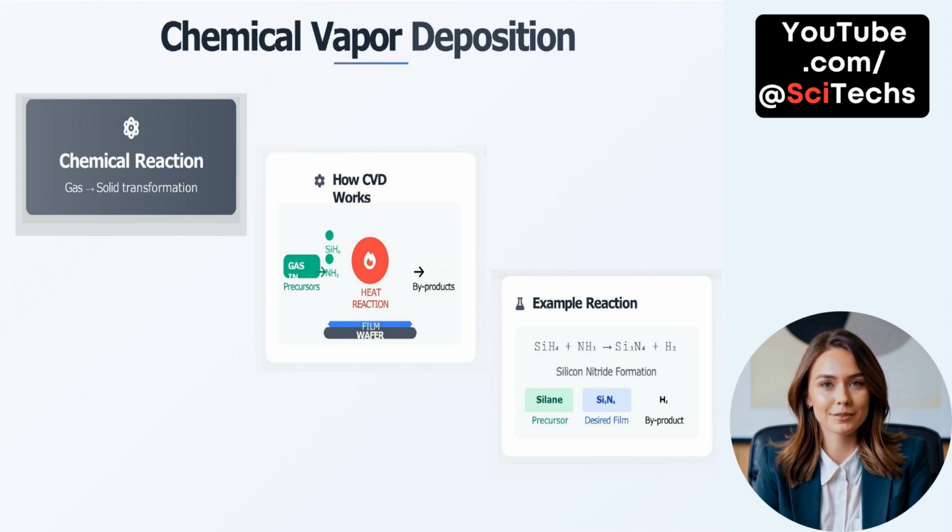Chemical vapor deposition. At the heart of chemical vapor deposition is a fundamental transformation, gas turning into solid. This gas-to-solid transformation is made possible through a series of carefully controlled chemical reactions. In a typical CVD process, gas precursors such as silane, SiH4, and ammonia, NH3, are introduced into the reaction chamber. These gases react when exposed to heat, triggering a chemical reaction that results in the formation of a solid film on the wafer surface. A common example is the formation of silicon nitride, Si3N4.